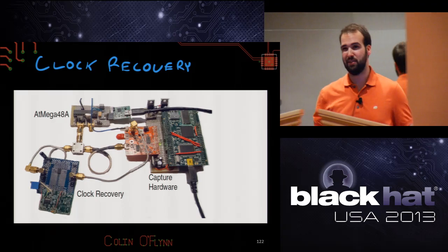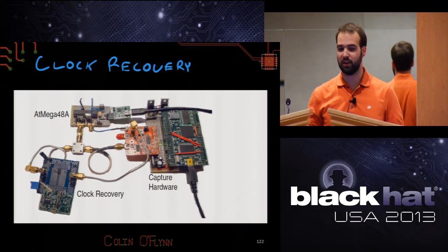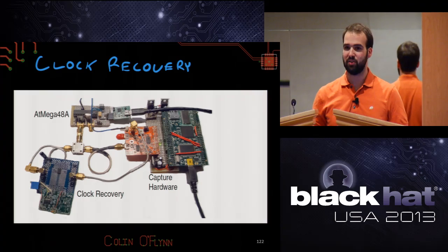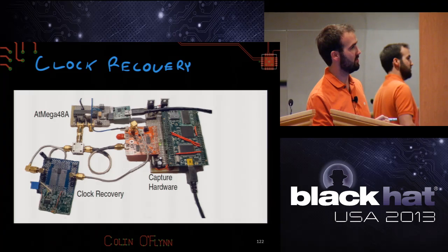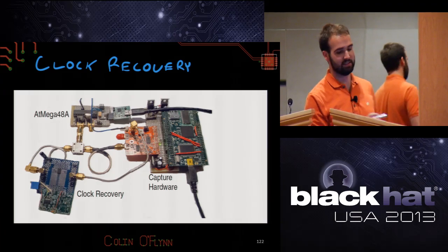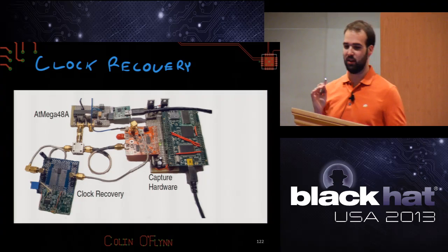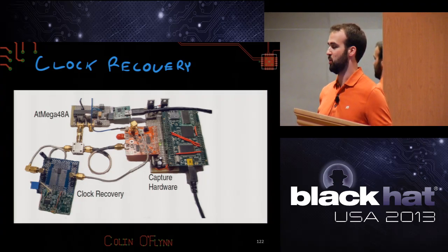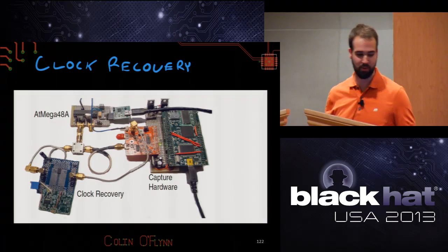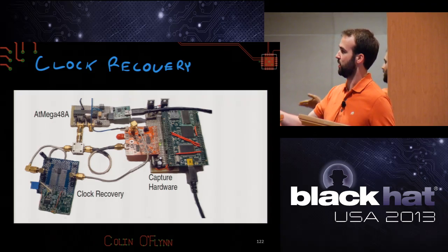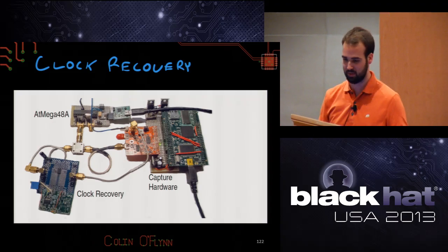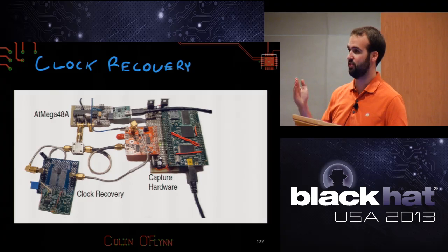This is pretty safe to assume for a lot of digital systems. Not all, because some systems may have internal oscillators inside the chip stopping you from tapping it. You can use a clock recovery system. I won't go into detail, but it's almost exactly like it's done in communications electronics. It's been known, again, 20, 30 plus years, this sort of idea. You can use that to recover the clock and then attack the system, and this works quite well, even if the clock changes during operation.